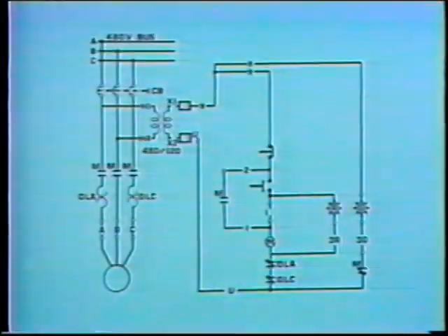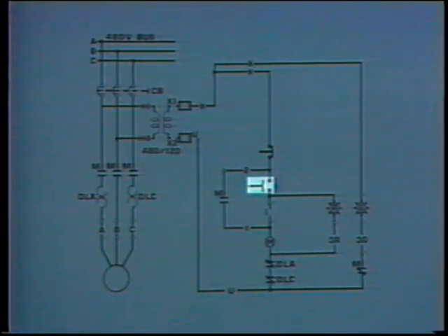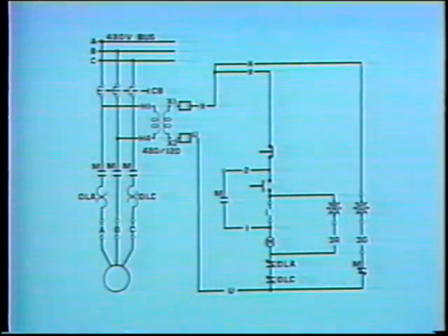Next, the electrician examines the possibilities in the control circuit. He needs to find a component whose malfunction would cause the motor not to start and at the same time affect both indicating lights. If the start button is malfunctioning, current could not flow through the operating coil and the main contacts in the motor circuit would not close. The motor then wouldn't start.